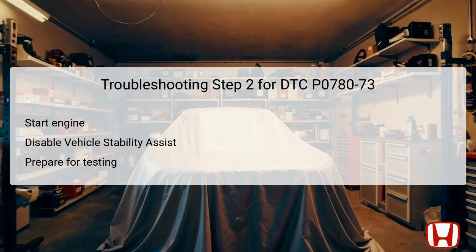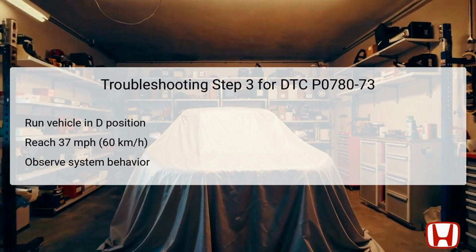This step is imperative as it sets the stage for accurate diagnostic results during the subsequent steps, highlighting any irregularities with the CVT. Following the engine startup and deactivation of VSA, the vehicle must be operated in D position until it reaches a speed of 37 miles per hour or 60 kilometers per hour.